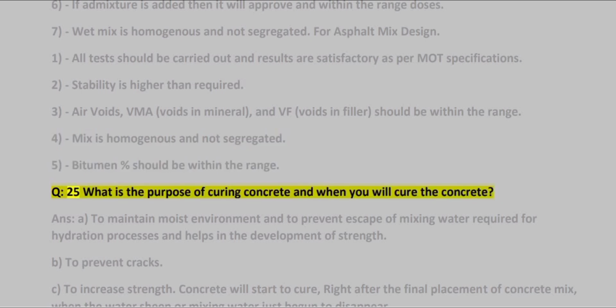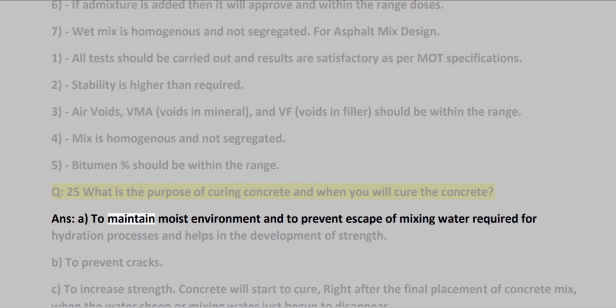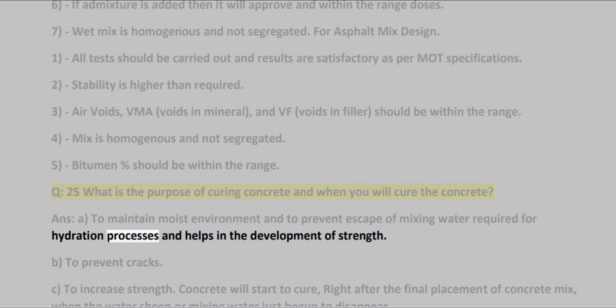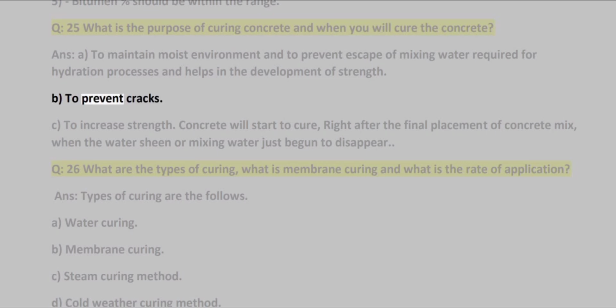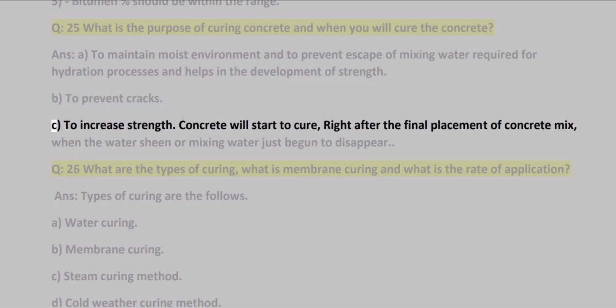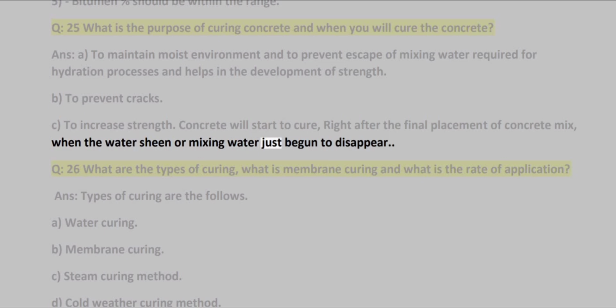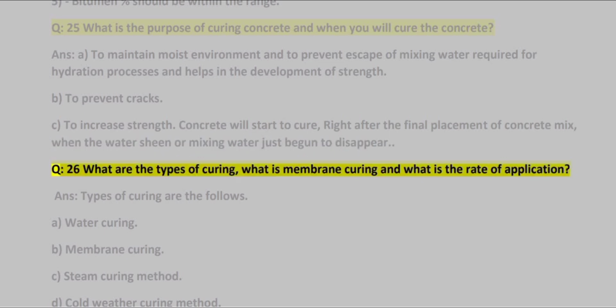Q25 What is the purpose of curing concrete and when will you cure the concrete? ANS: A. To maintain a moist environment and to prevent escape of mixing water required for hydration processes, which helps in the development of strength. B. To prevent cracks. C. To increase strength. Concrete will start to cure right after the final placement of the concrete mix, when the water sheen or mixing water has just begun to disappear.